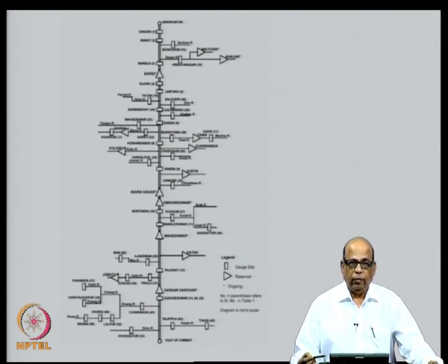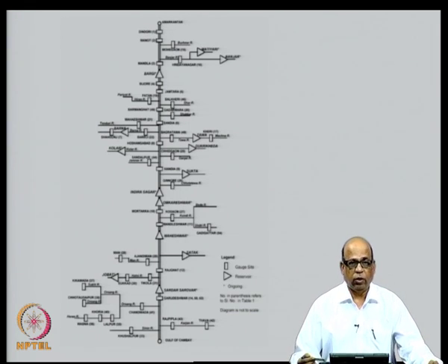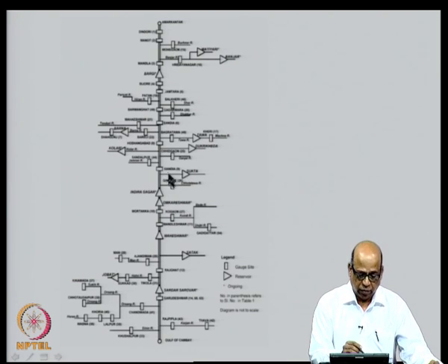And in the previous lecture, I have discussed the double mass curve for this particular system, and then we arrived at certain conclusions. As I mentioned, the double mass curve will indicate whether the flow at a particular gauging station, let us say you take Handia for example. Now, this flow has been contributed by these tributaries on the left and right side here, as well as what is coming on the main stream itself. So, Hoshangabad is here.